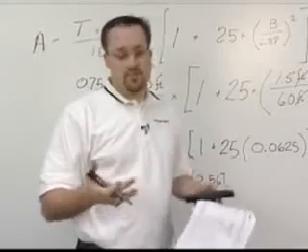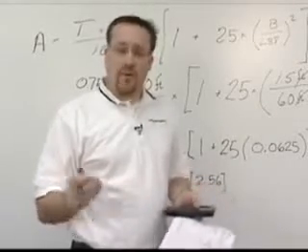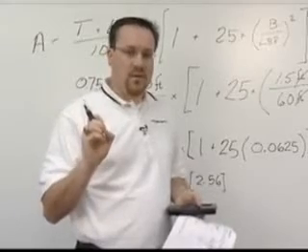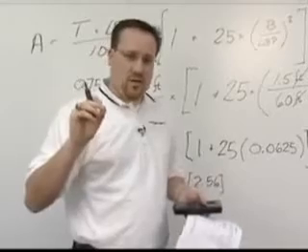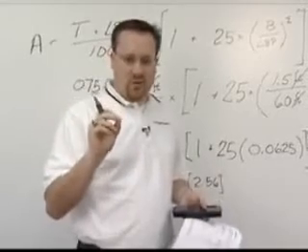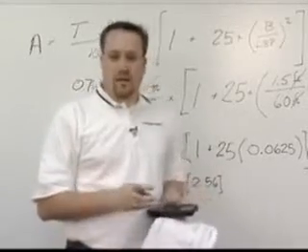In general, if it were me, I'd trend toward the larger rudder, but you're going to sacrifice some speed for the larger rudder, and in fact, when your rudder gets too large, it starts to actually hurt your maneuverability, and we'll see that when we do the next calculation.